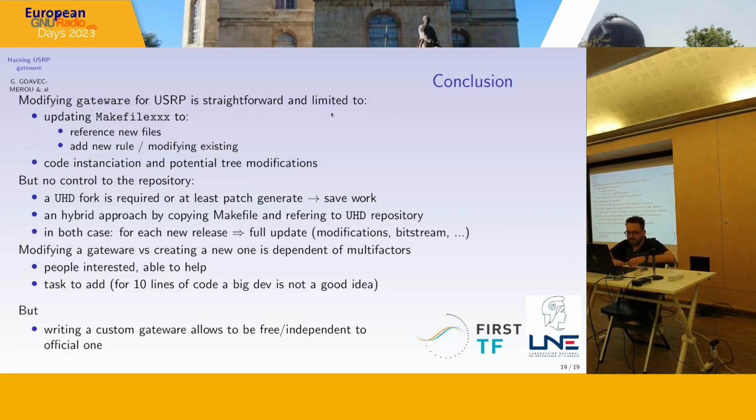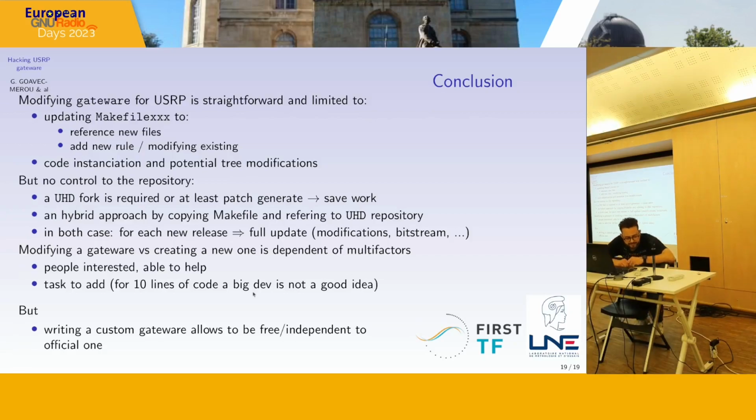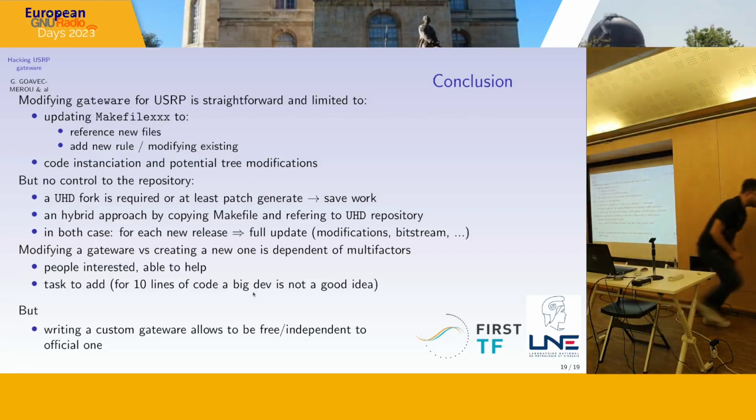Just a generic question, I would say. When you are playing with the gateware and software like this, of course, as you mentioned, you sometimes have delays that you have to take into account. You have the delay, of course, from the front end, for example. But after, how do you calibrate the internal delay of the unit? One way is simply to inject a known signal into the front end, to have your PPS, and to compare the sample between the corrupted sample and the known first sample.